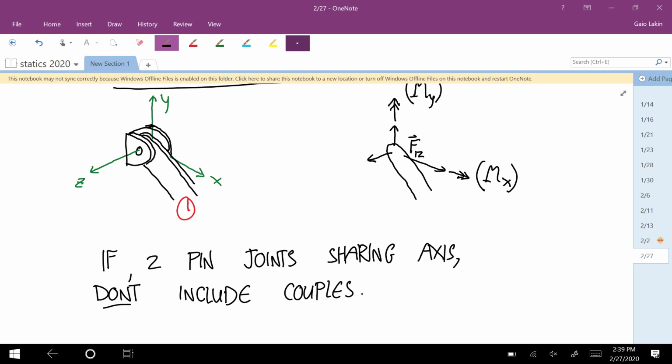How does this thing rotate? This might be the x-axis in some problems, or the y-axis in some problems. So you just have to be able to visualize how the degrees of freedom are restricted by the joint. Find the places where it can't translate or it can't rotate. That's where the loads are applied. Okay. And then the last one is easy. So that's joint category 5.